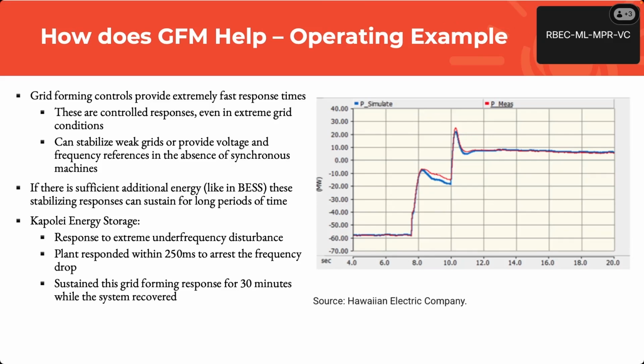Yeah, so this is a battery. This was charging, this was just the dispatch. At the time that the event happened, it was minus 60 megawatts, so it was charging. And then when the frequency moves, it goes up. So if it was dispatched differently, it would still do the same shape if the capability was there. In this case, if it's a 150 megawatt battery, if it had been dispatched at 100 discharging, it would have gone up until it hit its current limit and then stopped.